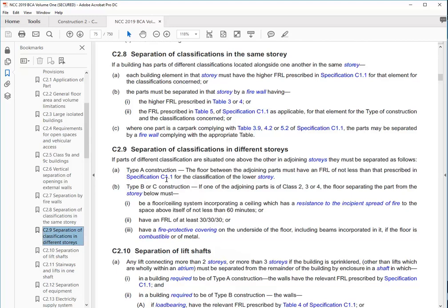Essentially, walls need to be non-combustible, and that means they essentially have to be masonry. As far as I know, you can't have timber-framed, fire-rated walls beyond a certain fire rating. You can get low fire ratings, but to get the higher fire ratings, you can't do that with timber, as far as I know, unless Kylie might know some tricks. So Kylie, do you know of any engineered timber wall systems that have the fire rating for...